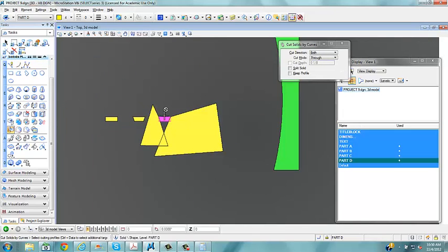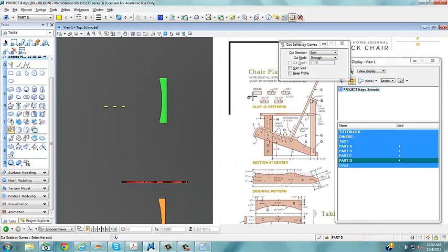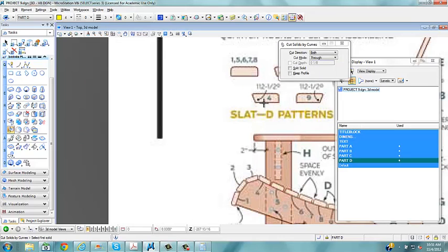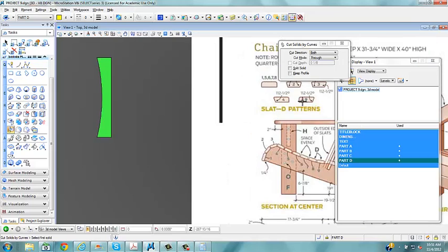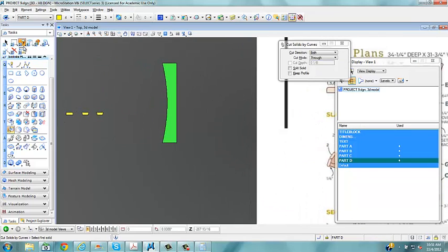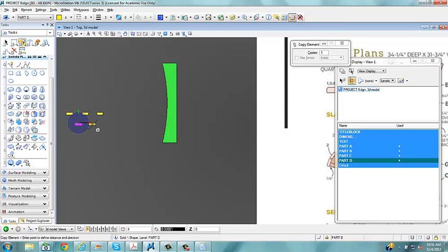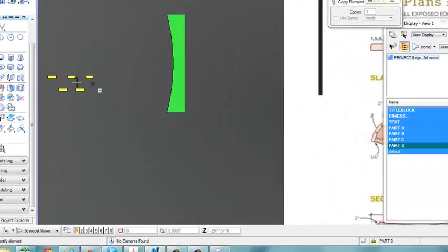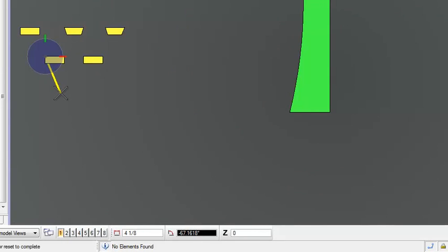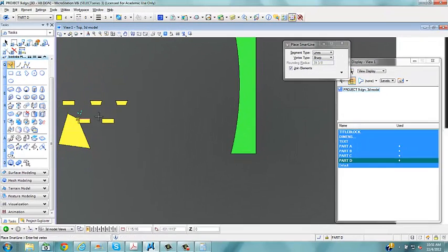So we'll do the same thing now. We're going to cut this solid with this shape and this shape, and I'm putting these in the same order as these. Now down below we've got 112.5 degrees on this side and 112.5 degrees on that side. So we'll copy this down here and here. Start a smart line. Minus 112.5. I'm always getting them backwards. 112.5 positive. And this one is negative 112.5. And we'll cut those.